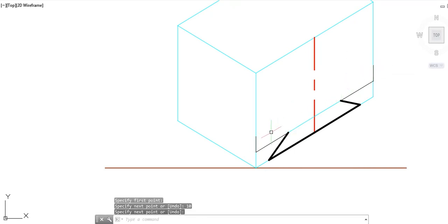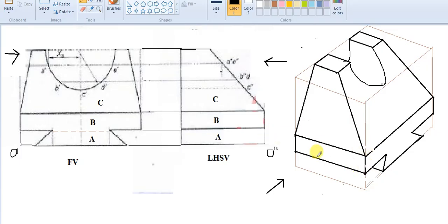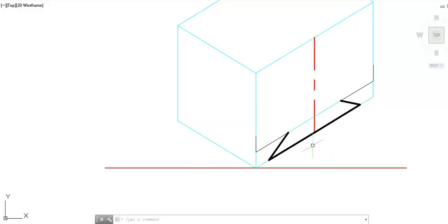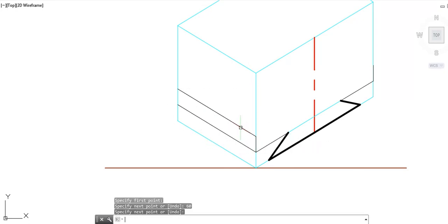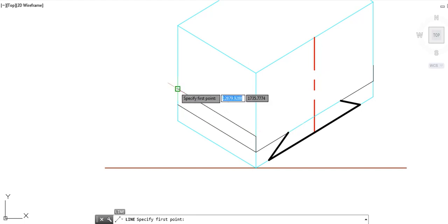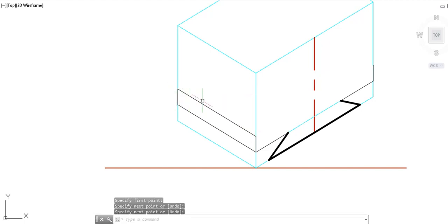Thereafter we can see clearly that these two lines now are going inside for the complete width available, which is 60, and then it frames a rectangle. So from there we will draw two lines of 60 millimeter each from the respective points, and then we'll join those two points, which makes the rectangle. So let me make them dark again. So that is how the things are done.